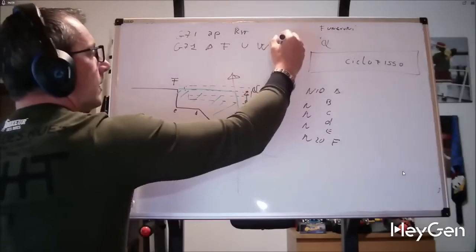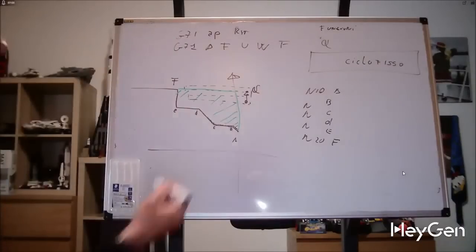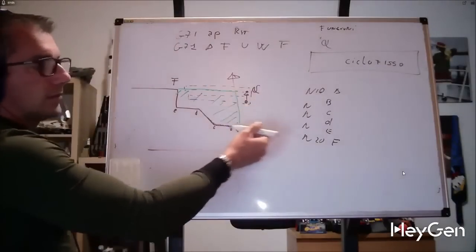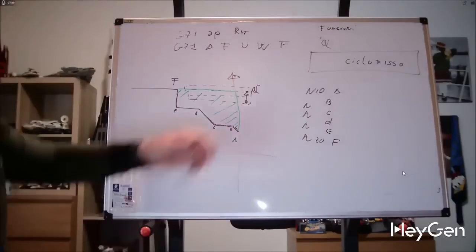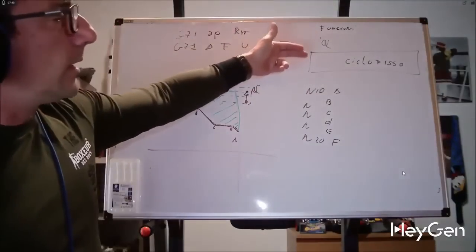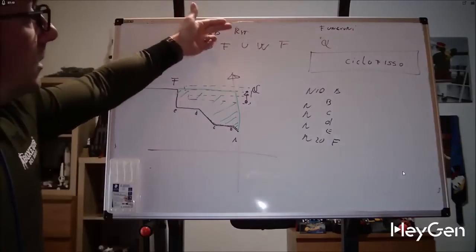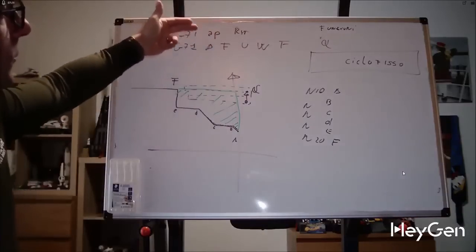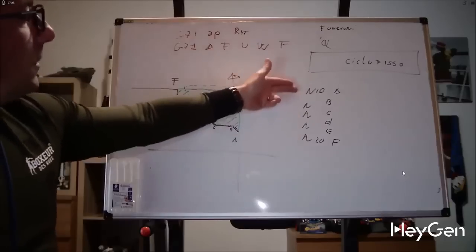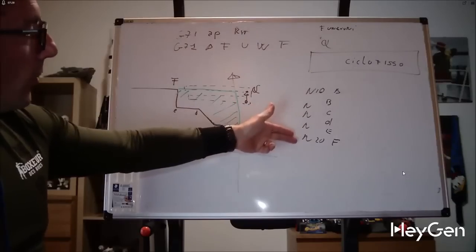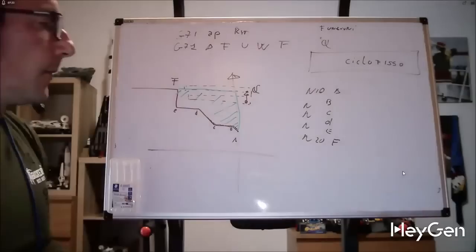Then I'll specify the feed rate, which will be a single feed rate for the entire cycle, with which we'll make these passes. So, the machine will read preparatory functions, then it will say, I have a fixed cycle that I will have to do with a 5mm pass, returning by detaching myself by 1 mm from the tool, following the profile that I will describe in the following blocks, between block 10 and now block 20. I will have to do everything at an F of 0.3, 0.2, 0.4.